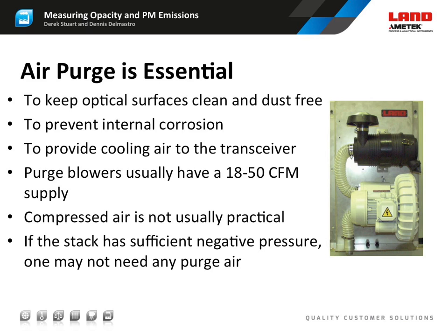If you should have a stack with a significant negative pressure, for example minus 10 inches of water column, you may not need an air purge system at all. And instrument air is always a possible option, though discouraged.